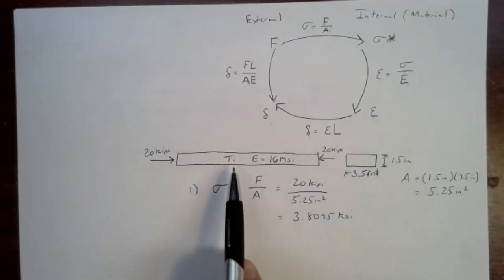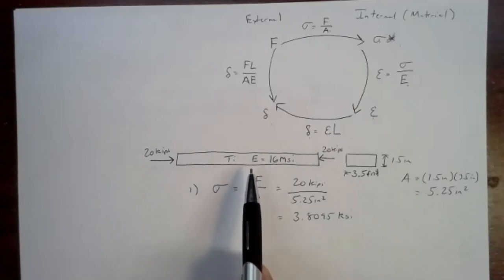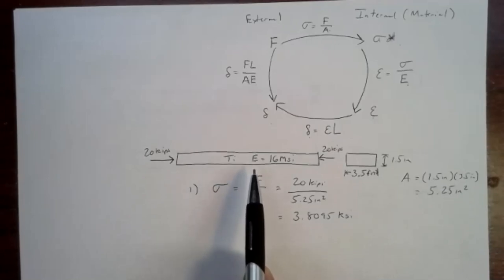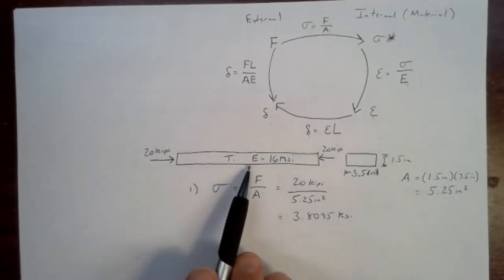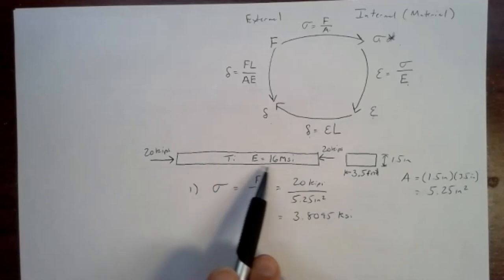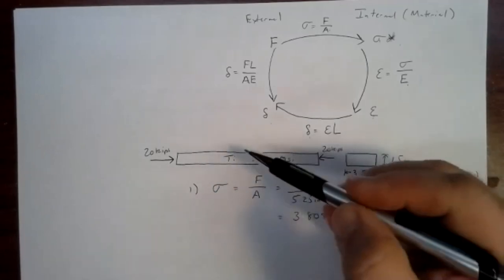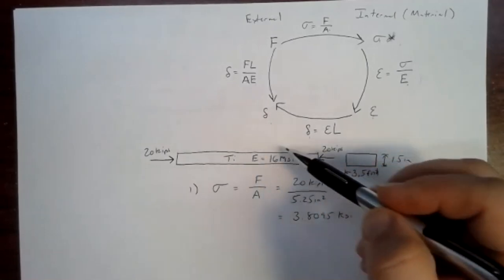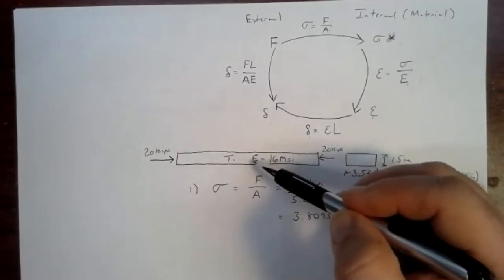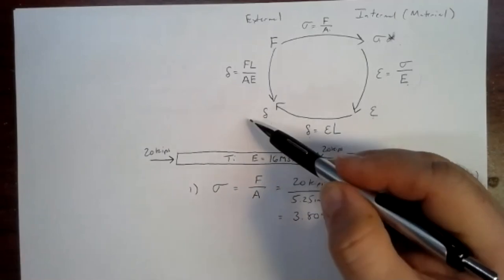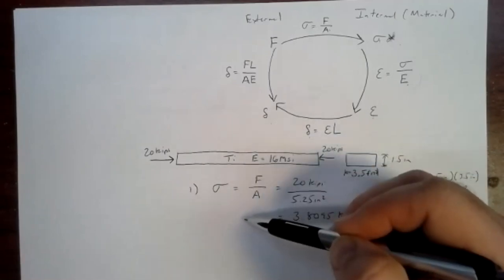When we pull on them hard enough to reach that maximum stress, that's when things tend to break. On compressive stresses, we tend to have materials fail by buckling, meaning that it doesn't fracture. It tends to kick off to one side or the other and change its shape that way.